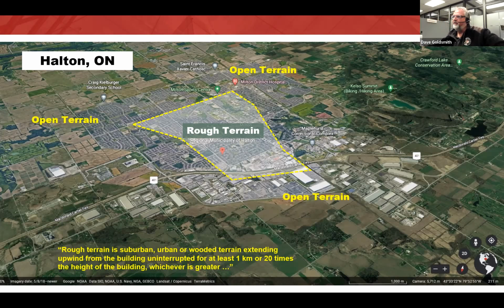and they use tables from the code, historical tables from the building code, that say, for an area, this first table is for an area with 1 in 10 hourly wind pressures not higher than 0.4 kPa. We recently increased the requirement to 1 in 50, but so the default glass tables that a lot of companies use, they don't take into account places like Vancouver Island. And we'll get into that a little bit more later about what the implications are there.